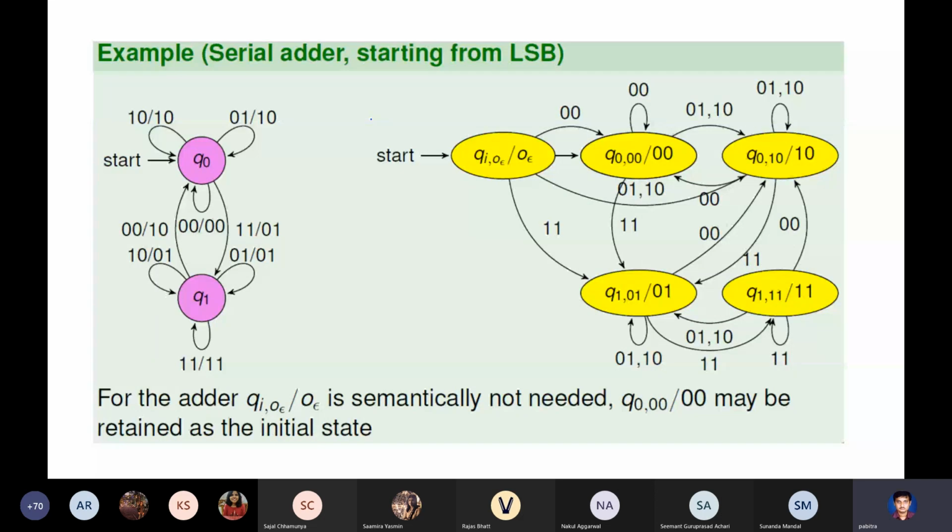I'm not explaining why it is like this. You know that I told you that you have to remember the index, the parity of the index. But maybe let me quickly tell. There are two inputs, X and Y. For every bit of the two inputs X and Y, you have two outputs, carry and sum. Depending on when the carry gets generated, there is a transition. You have to look at the position where there is a transition, and from that you move to a new state.